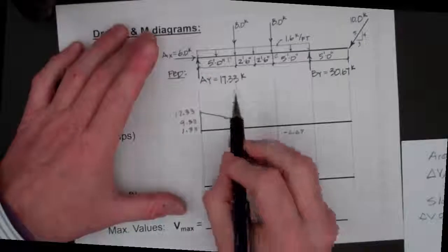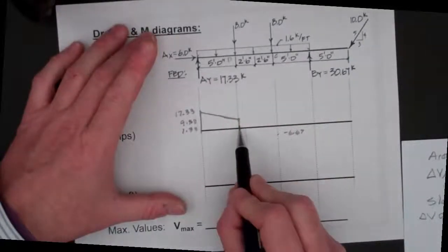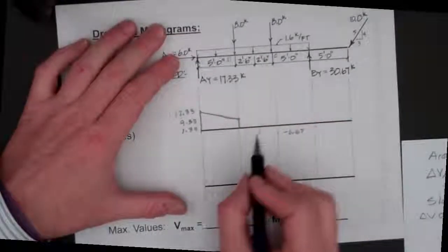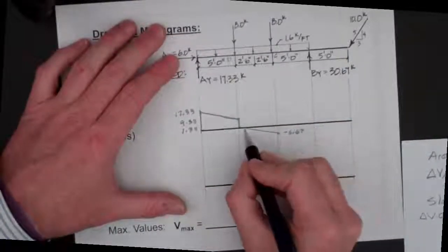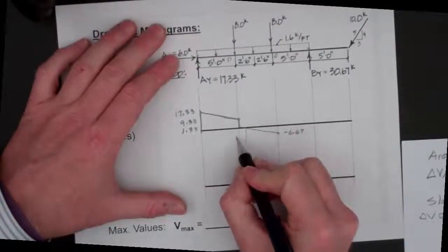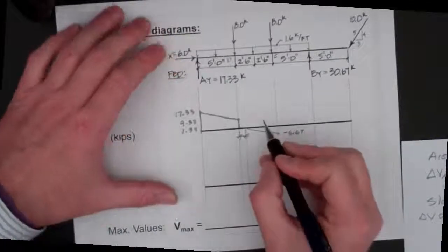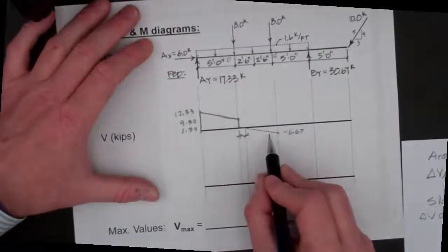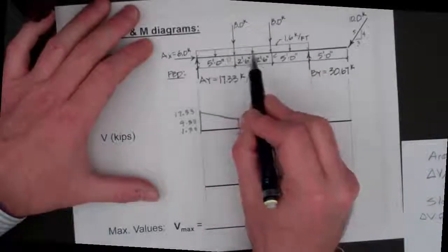And note again that the value of the load is equal to the slope of the shear, which in our case is a negative constant 1.6. Right there, there's our straight line. Okay, so now we need to know this distance, and there are several ways to find out where the line crosses the axis. The simplest way is to realize that the slope of the shear is equal to the value of the load.